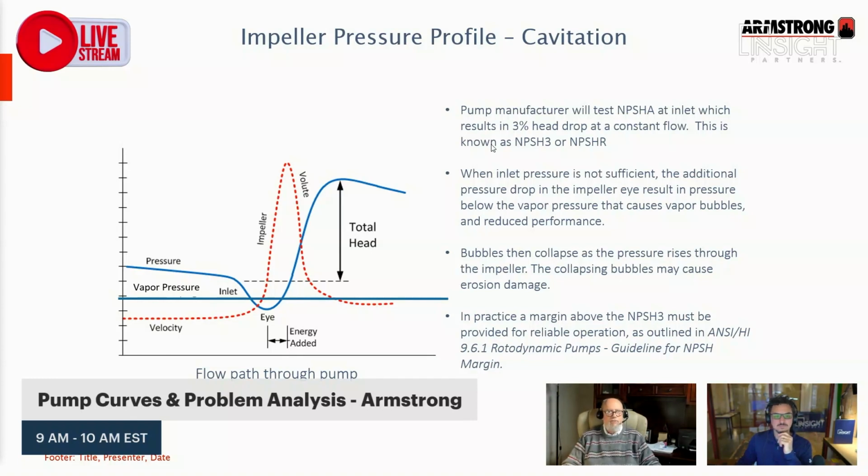There's a couple manufacturers out there that will tell you, oh no, you only need 25%. I'm telling you right now, if you design with a 30% margin, you and I are going to become best friends, and you're not going to have problems with pumps.